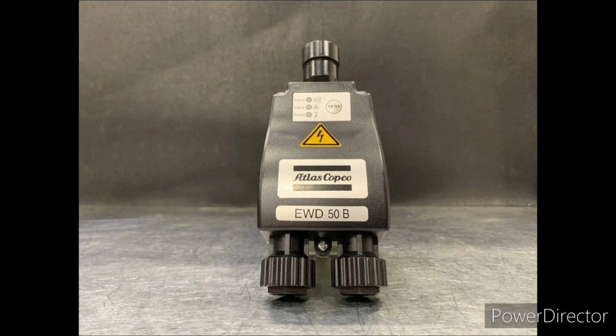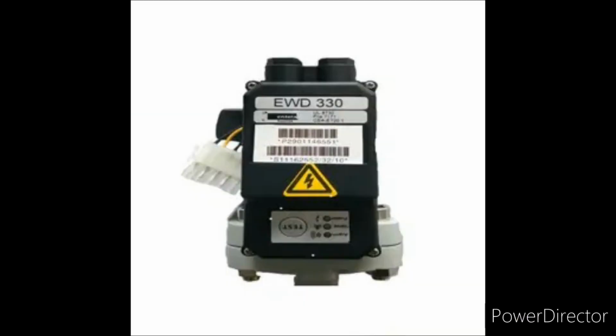Okay, so automatic drain valve versus manual drain valve. What is the difference? I told you already before. Before we jump into the difference, know that most air compressors come with a manual compressor tank drain. It is located at the lowest part of your air tank. The water is generated by the pump and is taken into the tank by compressing the air. It goes to the lowest part of the tank, hence the drain is located there.